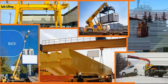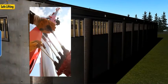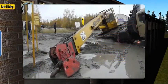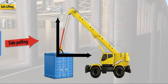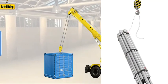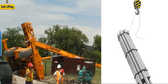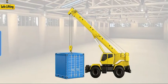Cranes are designed to carry a lot of weight, but they have their limits. If you're a crane operator, you should be well aware of your crane's weight limits, but you can still cause accidents by picking up or lowering loads the wrong way. For example, lifting a load from an angle known as side pulling can cause the rope to snap and slip the load out of the guiding pulleys. Side pulling can also make the load swing wide from where you want it to be, and swinging too far wide could snap the cable or pull down a mobile crane. To avoid this, always center the hook and line over the load before lifting.